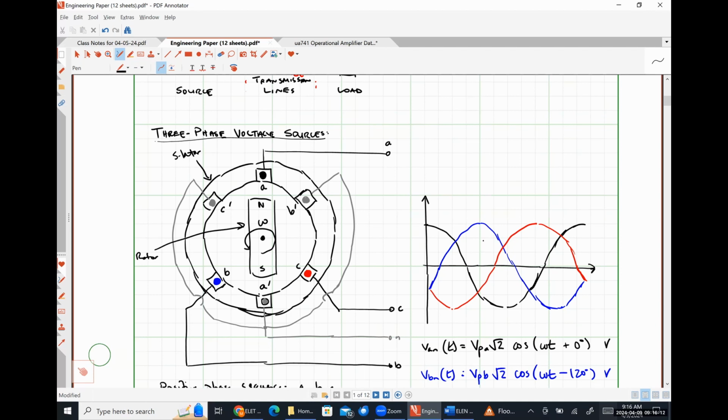So a DC motor, you only have a DC voltage as an input. You have to have a thing called a commutator, which is used to effectively switch the direction of the current constantly so that the motor doesn't turn like this and then like this back and forth over and over again. The more pieces that you have or you divide your commutator into, the more smoothly the motor spins.